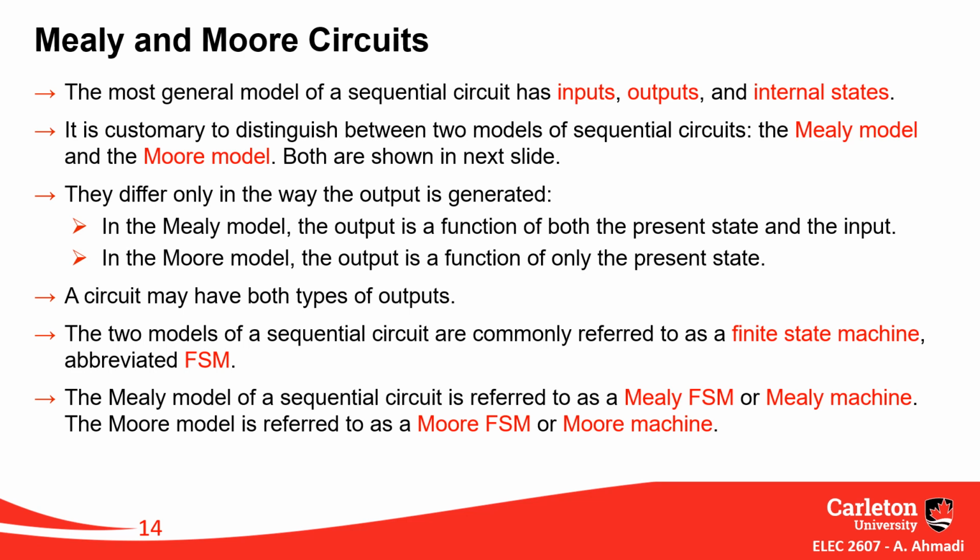But this must apply to all states, right? If for all states of a finite state machine, of a state diagram, of a circuit, if you check every single state and see, just knowing which state your machine is in right now is enough to make conclusion what is the output, that circuit is a Moore circuit.